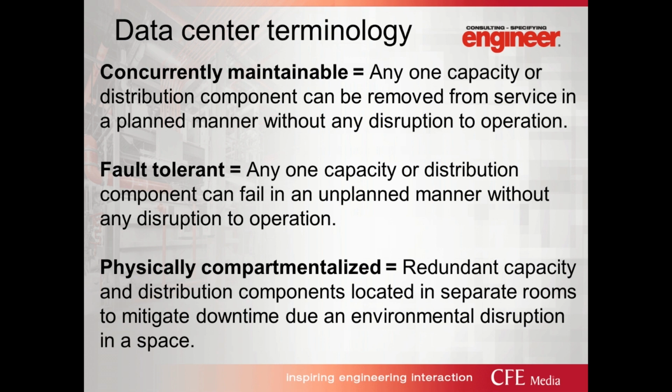Concurrent maintainability, one thing that I think a lot of people misunderstand, is that it's being able to have a capacity or distribution component removed in a planned manner. A lot of people misinterpret that to be an unplanned event. So concurrent maintainability means that if you have a method of procedure, you will be able to remove a component and still keep your uptime.